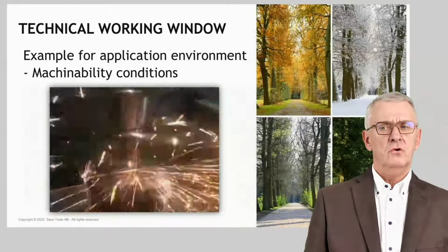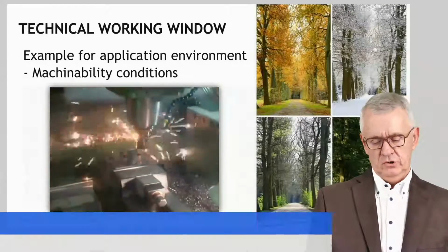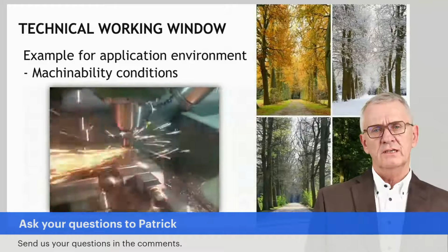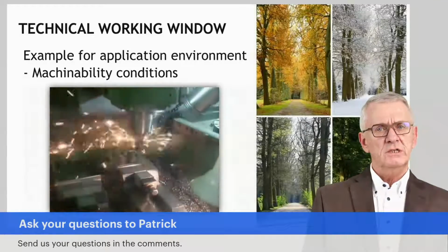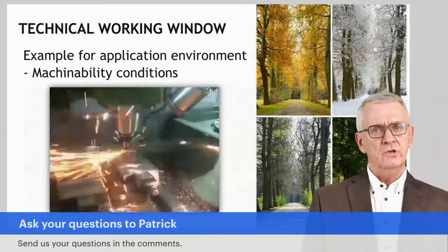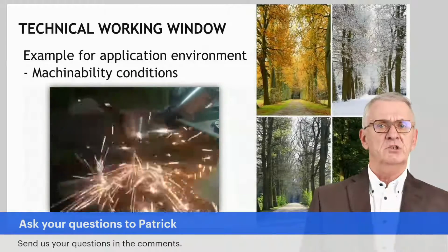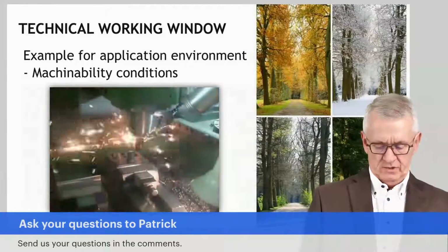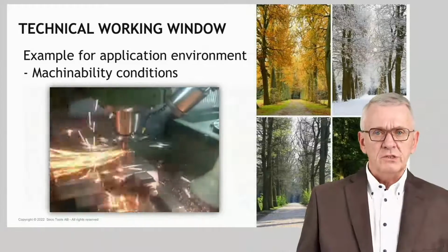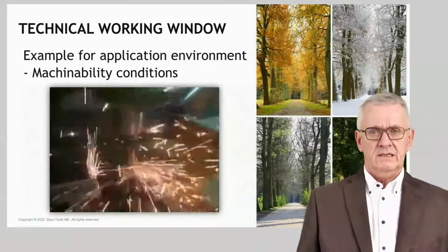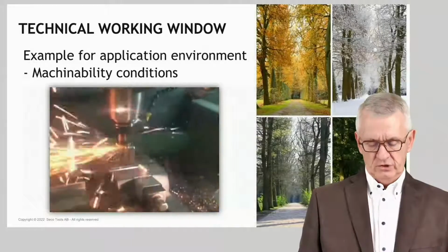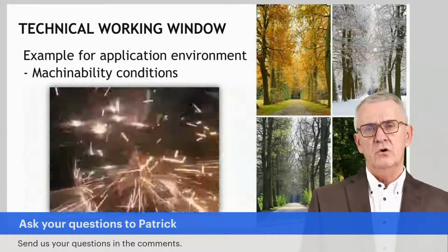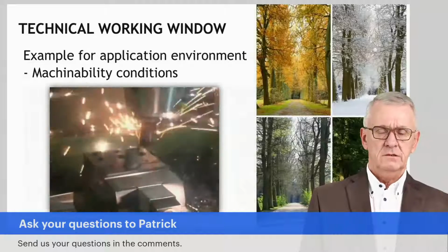Because if you do all your preparation, all your production engineering work, and you consider that the machining is going to be done with high pressure cooling, but for some reason at the machine tool itself there is no high pressure cooling, that has consequences. So the environment in which you do machining must be known and must be respected.